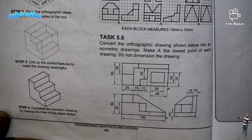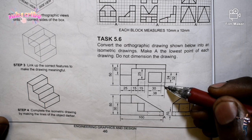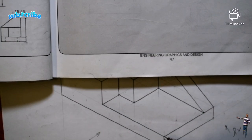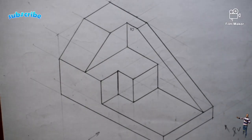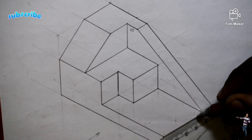You understand? So to get that hole, or the square hole, we are told to go to the right from point A, coming this side, is 32 millimeter. My point A is that one. Remember, we see it clearly there in our top view. That is why we are going to dimension right from the top view. You understand? So the set number is 32. So I come here. Where is my 32? This is my 30. 32 is that one.